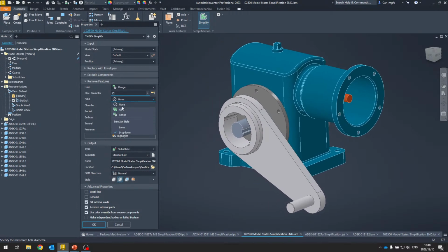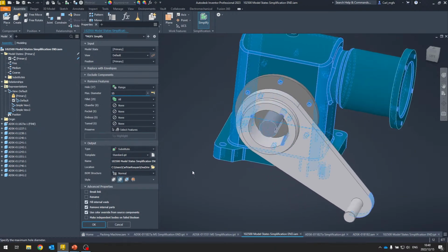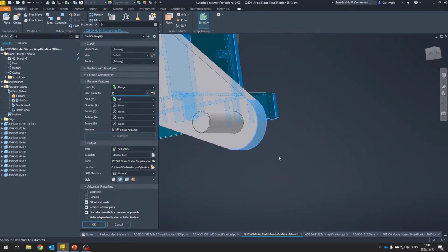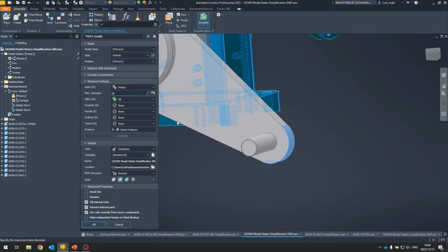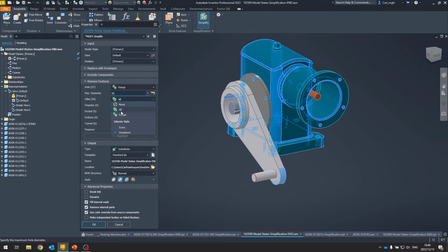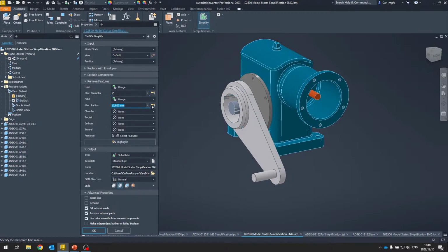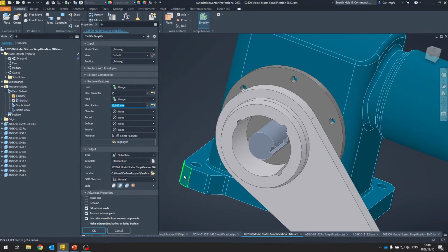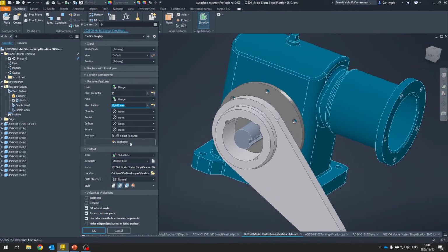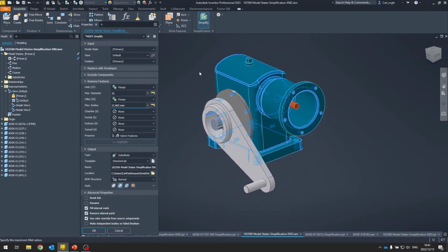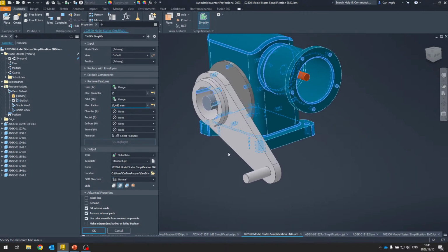And let's say we remove all the fillets. There's an option to highlight that will then highlight all of the features that will be removed. You'll see that because I chose to remove all fillets, the round on the end here is being removed, so that may not be desirable. So I'm going to go all within a range, so let's say all fillets equal to or smaller than that corner round. Let's highlight that. That looks a little bit better there, not removing detail on the handle.